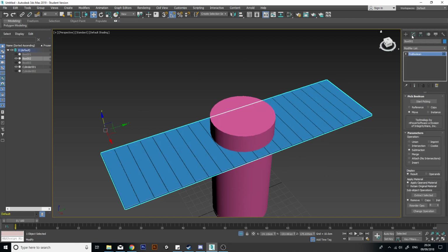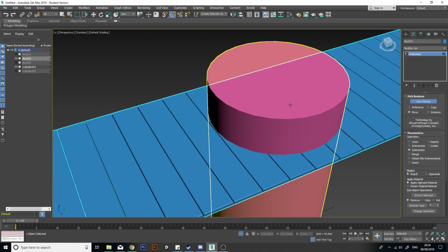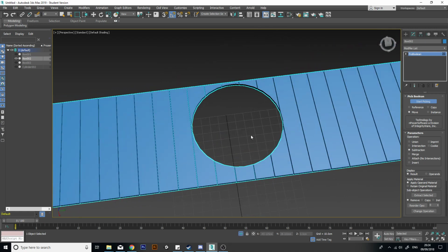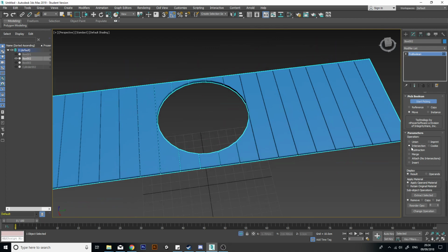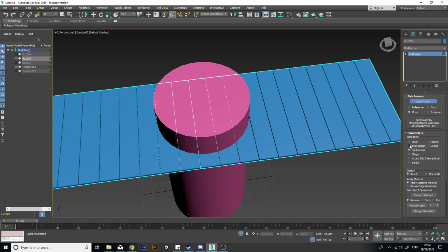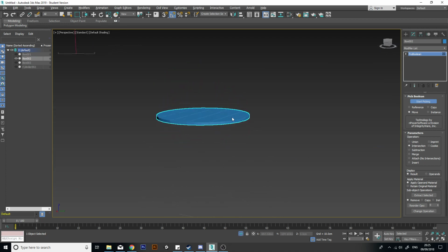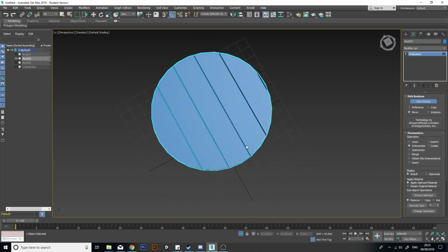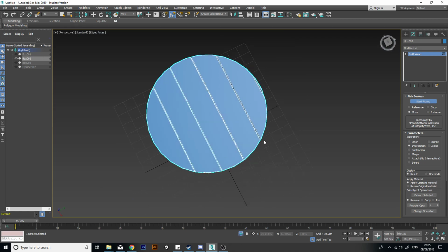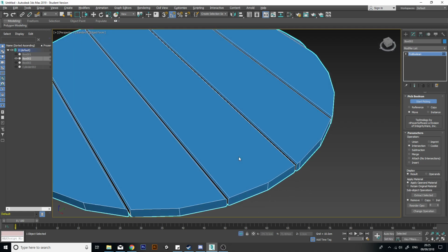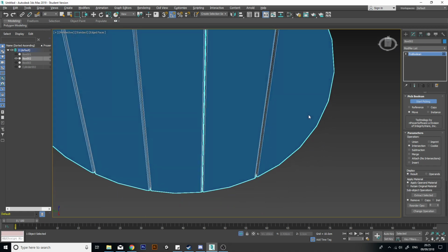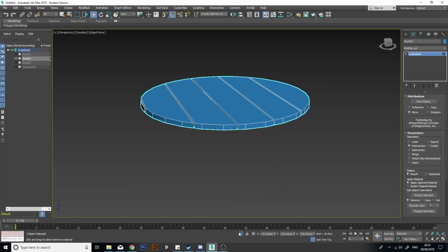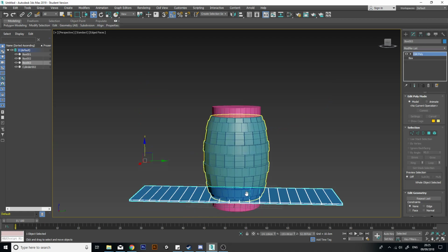Now, this is a pro boolean. I will pick this cylinder, and by default it will cut a hole, but that's the exact opposite of what we want. What we wanted was intersection, not subtraction. So now we have used that cylinder to cookie cut out of our object. That's actually done a very nice cut there. It can be sloppy and create some very nasty cuts and some very nasty topology, but that was actually quite beautiful. That's exactly what it should be used for.